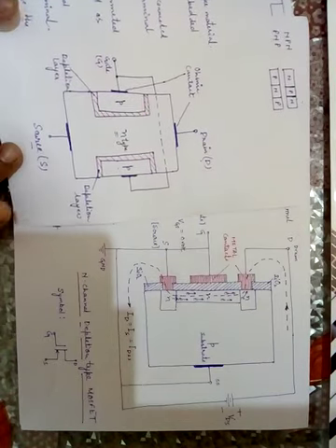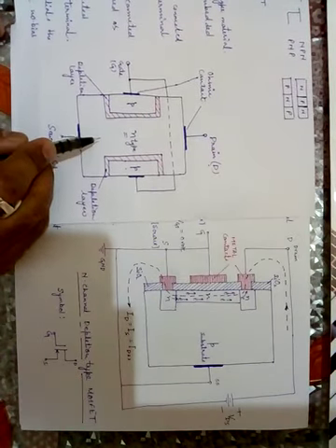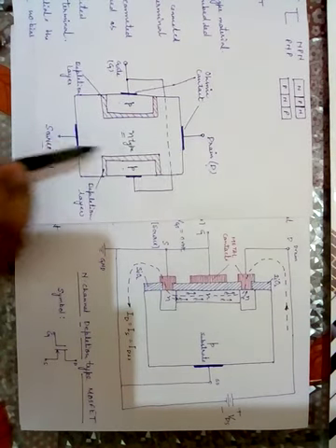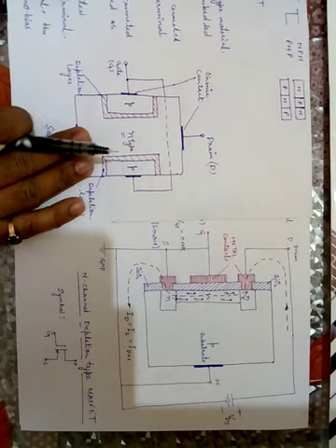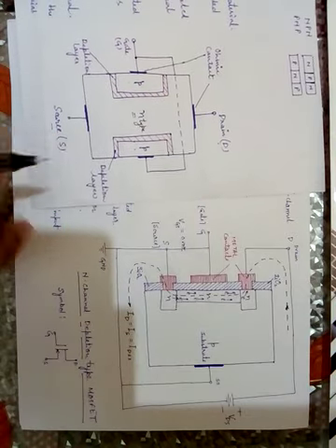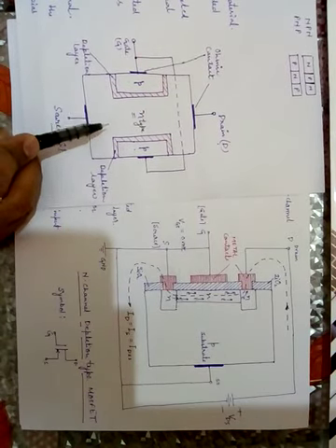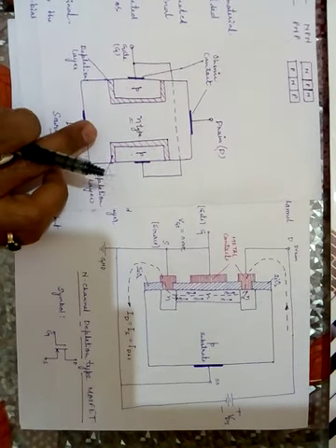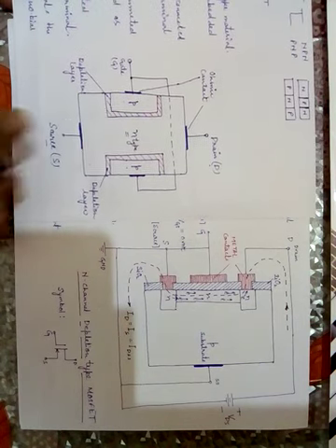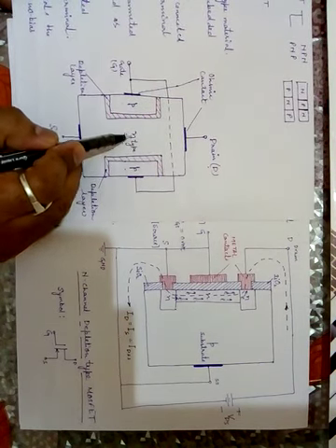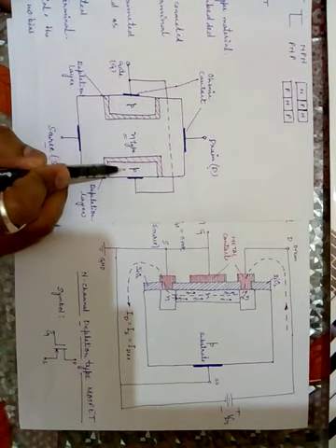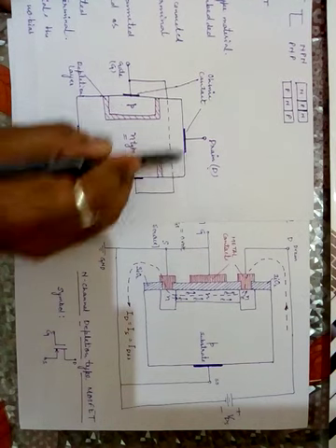This is the structure of an N type JFET. Why is it called N type? In both I am taking N type because the whole current flowing from drain to source, in the JFET as well as in the MOSFET, is just because of the electrons, which are the majority carriers in N type. This JFET is also N type, but the construction is a bit different. In the midway it is all N type, and on both sides I have taken P, and the P is not taking very much area in that N type.